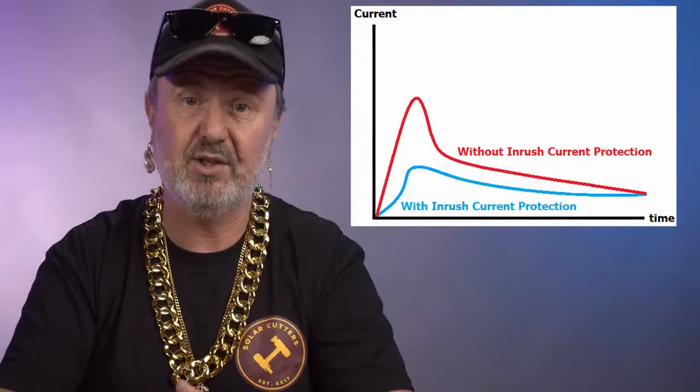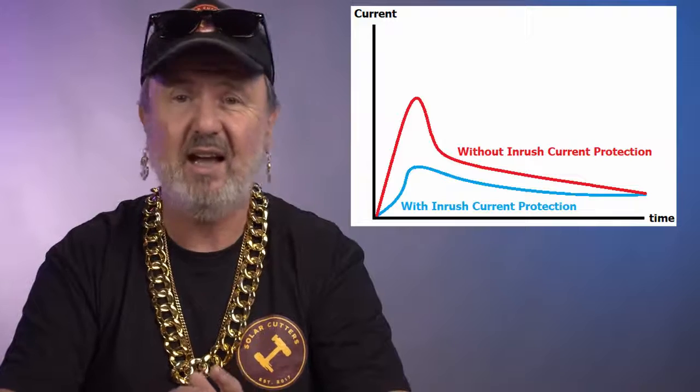So your dishwasher might turn on, it'll circulate a bit of water, little pump runs, very small load. The big pressure pump comes on, boom, it comes on with a surge, and I'll talk about surge in a second. And it's also got power factor because it's a pump. Then the water heater comes on in the dishwasher and starts heating water. So there's another 1200, 1500 watts of demand. So the two things together could be quite significant, could be a couple of kilowatts or more.